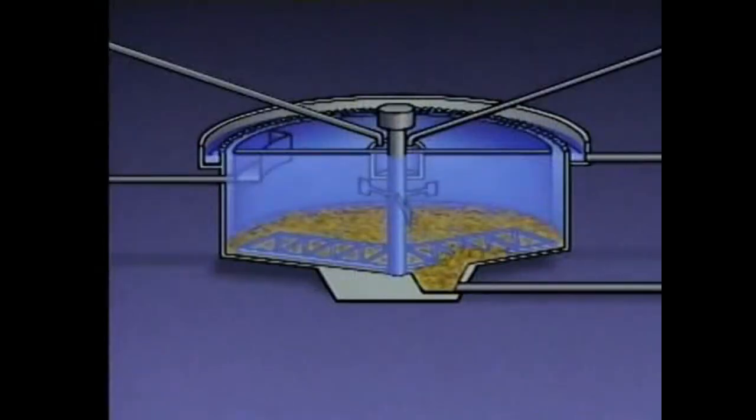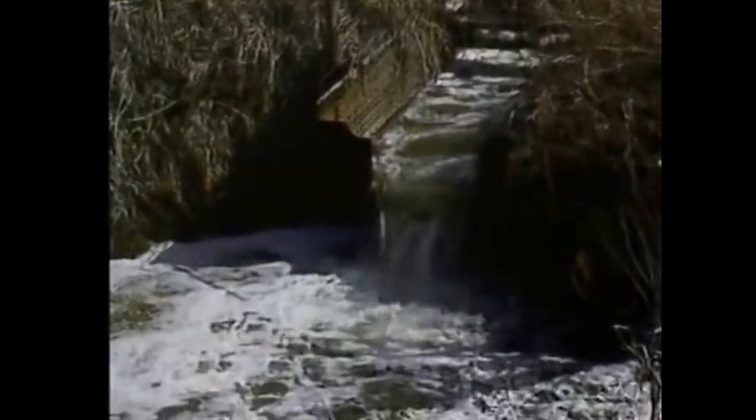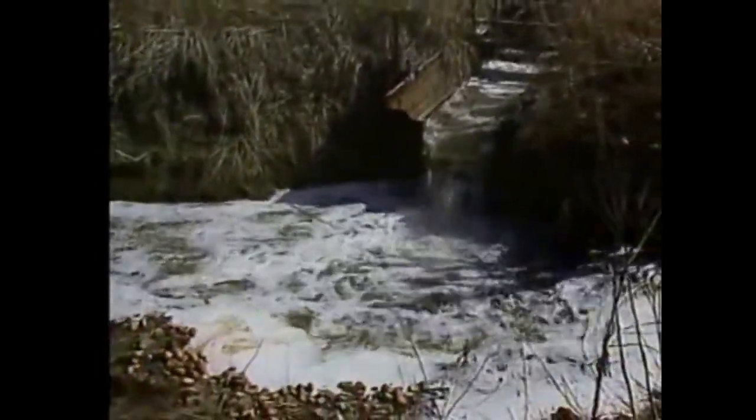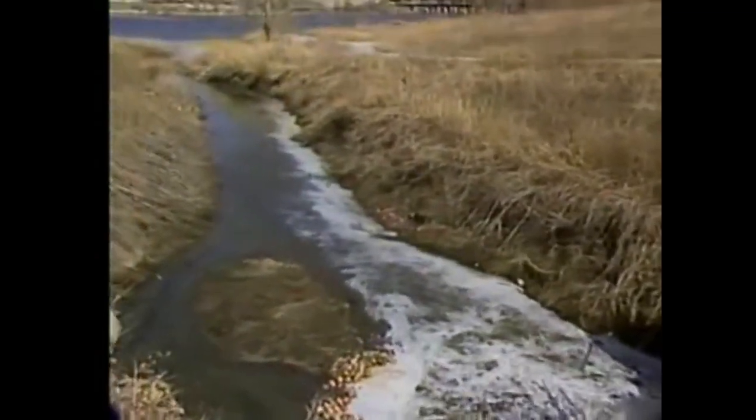The sludge blanket in a clarifier acts as a filter to trap suspended solids in the wastewater. However, if the sludge blanket level gets too high, solids could be carried over into the next treatment stage. Another result could be insufficient removal of impurities from the wastewater leaving the treatment system. Also, the pH of the water leaving the treatment system could be affected.